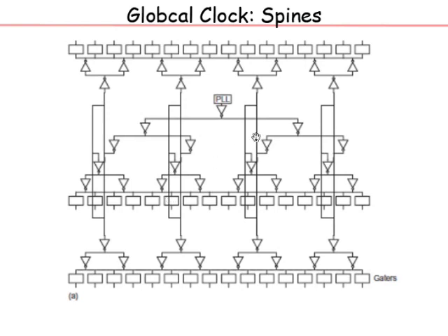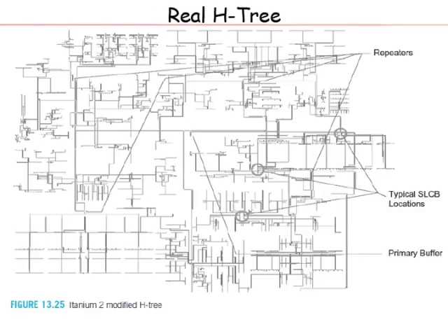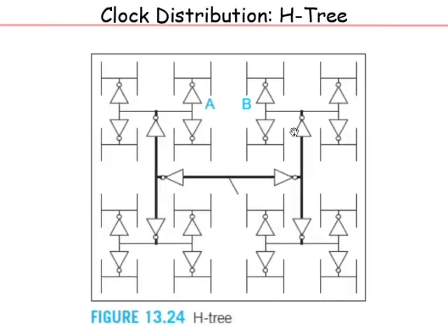So it may not be very apparent, but from the PLL to each of these local clocks, the clock distribution is broken up into two pieces: a global clock distribution network and a local distribution network. Global is coming here and reaching the regions. You break up the chip into regions, and then you go to that region. For example, here this is the global clock distribution.